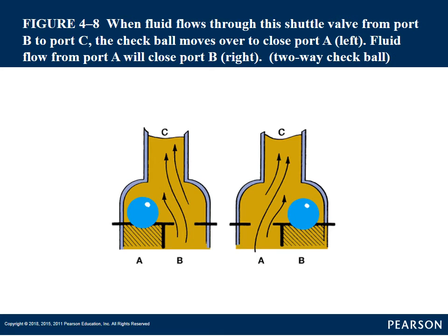In a two-way check valve situation, it depends on which way the fluid flows. Say the passage is coming from B, as you can see, it'll push fluid up, it'll move the check ball into the one hole, so fluid doesn't backfeed back down A, because that may be connected to some other circuit that we wouldn't want fluid flowing in at that point.